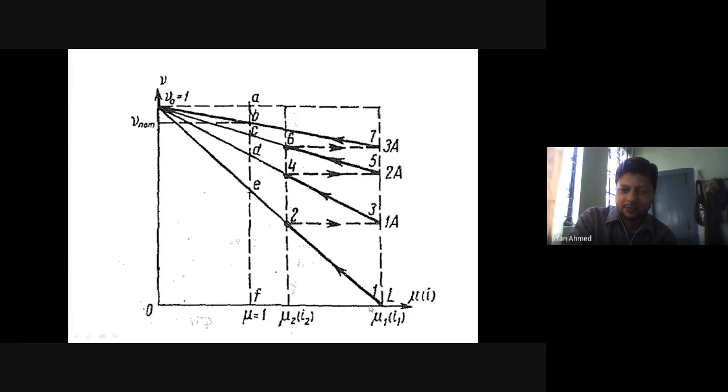Ideally, you want the motor torque to be as much greater than the load torque as possible so that you can get fast acceleration of the motor. But you have some limits. The upper limit is because of your commutator. The commutator is not allowing any more current than I1 to flow. So the commutator has decided this upper limit. Now the lower limit is in your hands. You can have it at point A, at point B, at point C.